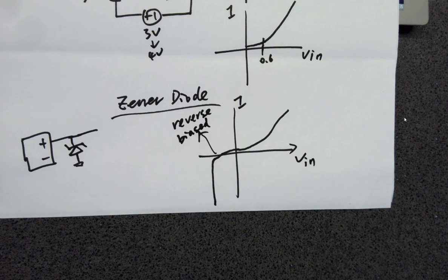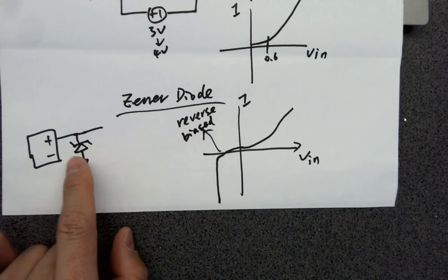Keep in mind. So sometimes I have all the different components in the drawer in the lab, and students were trying to search for some diode to be used for their power circuit, and they couldn't find it, and directly grabbed a Zener diode from the drawer and plugged it into the circuit. That shouldn't be used that way. So Zener diodes are always being used as a voltage stabilizing circuit.